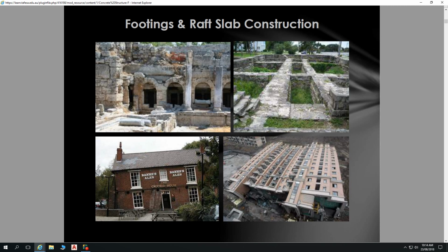A major difference between those two, though, is if I had a concrete corer and was cutting a hole through any sort of beam, I wouldn't want to do it without understanding how it all works and what I'm going to hit. But let's say I did. If I chopped through one of those strands in a pre-stressed beam, it's not going to be as bad as in a post-tension one.